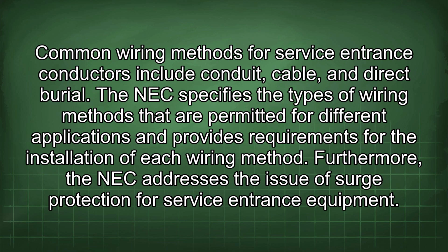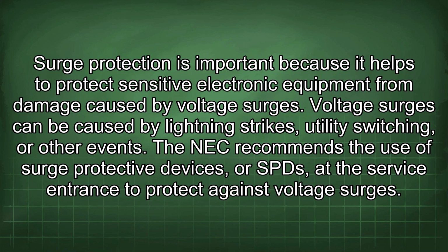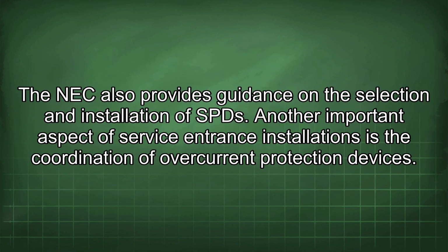of each wiring method. Furthermore, the NEC addresses the issue of surge protection for service entrance equipment. Surge protection is important because it helps to protect sensitive electronic equipment from damage caused by voltage surges. Voltage surges can be caused by lightning strikes, utility switching, or other events. The NEC recommends the use of surge protective devices, or SPDs, at the service entrance to protect against voltage surges. The NEC also provides guidance on the selection and installation of SPDs.